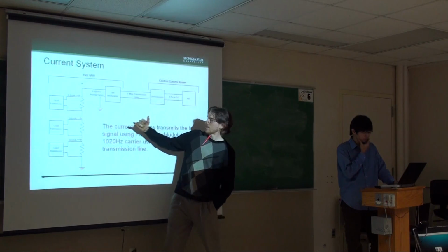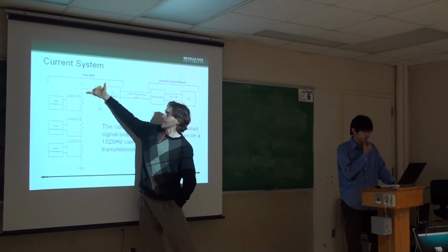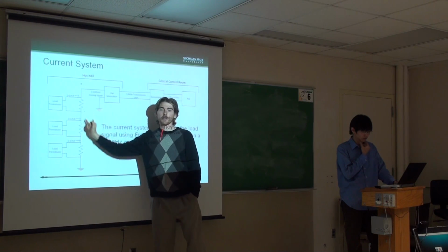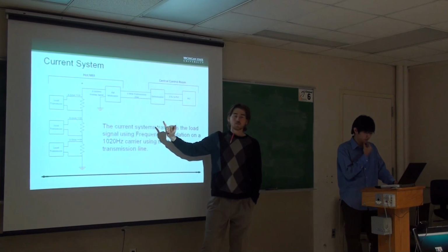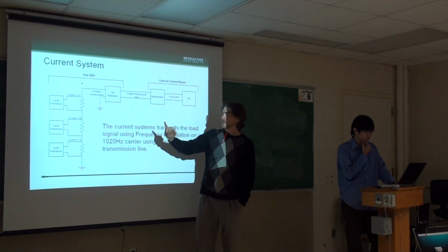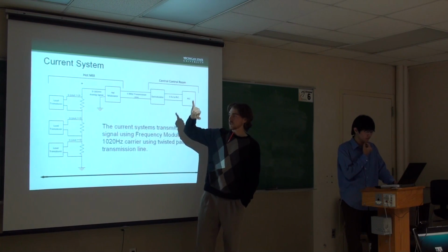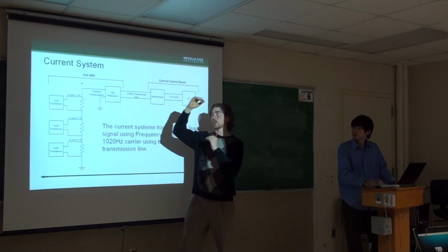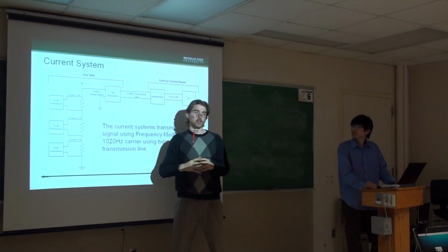So if you add up all these resistors that are in series, you're going to get a potential difference between this node and ground, and this potential difference varies for the hot mill between 0 to 100 millivolts, and that signal is an analog variation which linearly represents the power variation from 0 to a peak value in the hot mill, which then goes to a frequency modulating device.